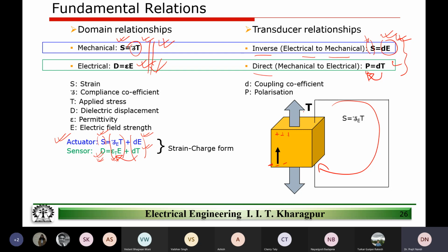And then we are applying the stress, because we have shorted them, any additional charge is sucked away by the wire. We are not allowing any additional charge to develop, because we are ensuring that the potential at the top plate and the bottom plate, these 2 plates, is the same. So no additional charges will appear even though we are applying a stress.